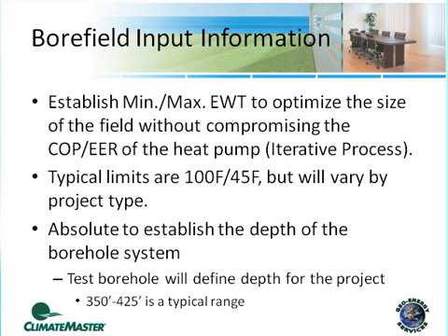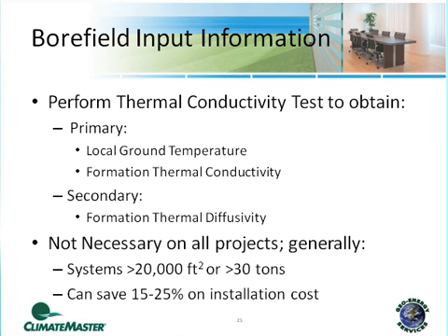And then the last point here, we need to decide how deep we're going to go on the borehole system. Typical depths across the United States for a project are going to be 300, 350 feet up to about 420 is a typical range. I've seen projects where we go to 200-foot boreholes per depth. We'll also have projects where I've seen 500 to 550 feet per hole on the depths. So you do certainly have those types of very wide extremes, but if you look at the bulk of projects that are out there, 350 to 450 feet deep is an average.